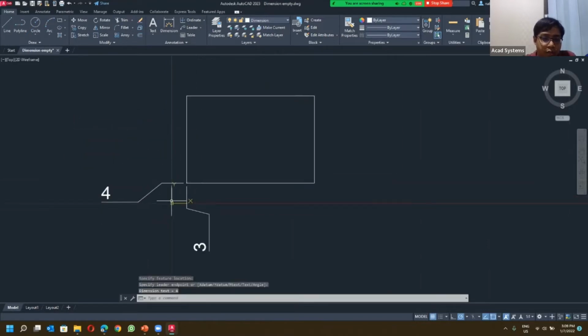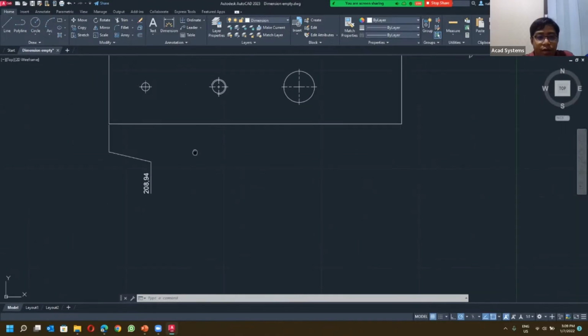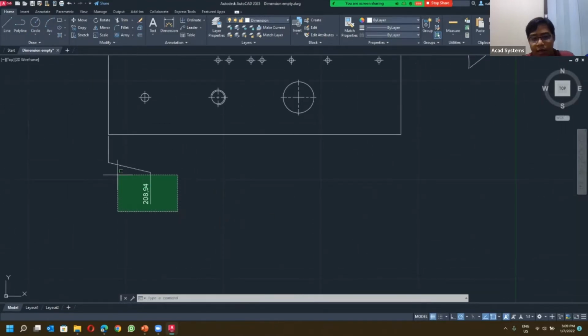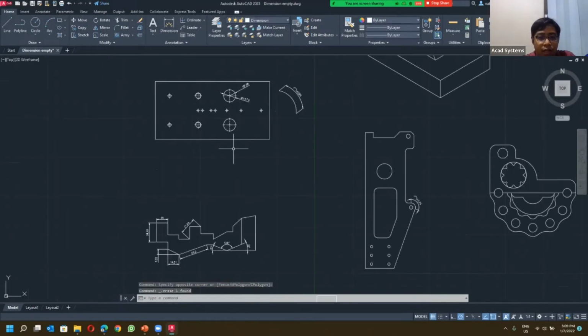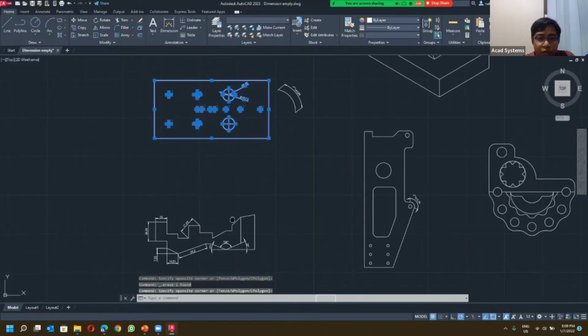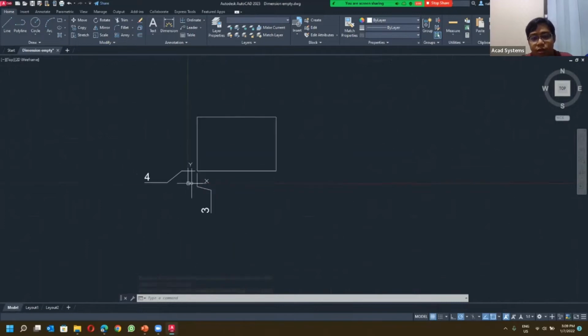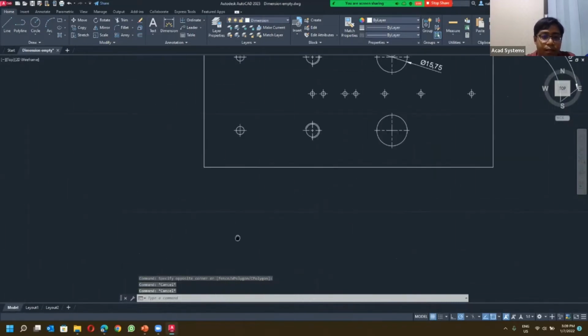The coordinates usually are based on this UCS, right? So this origin point, x and y, we call it the UCS. If I have some other direction which is created from here and I want this to be my origin point, either you move this entire object so that this point sits at the xy origin, or you can move your origin to this point.